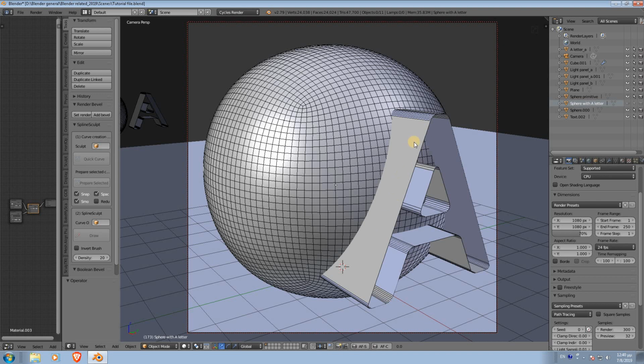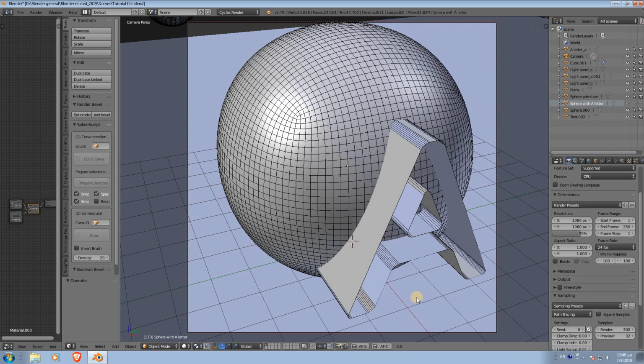It's extracted from the shape of a letter that's created with the text editor of Blender. It's very easy to do. You extract a silhouette, and then you bevel it here. One thing that we have to be very careful about is to have the objects be united, rounded, without sharp corners, because the add-on has difficulty working with sharp corners.